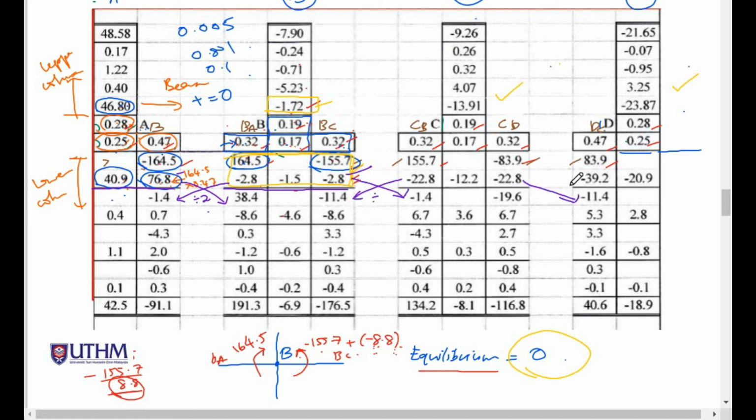Okay, divided by 2. And the process is repeating. Repeat process. Okay, so let's say here is 1.4 negative. It is the repeating process. This is 1.4 at joint A here, and negative, so it is counterclockwise, 1.4 negative. So we need an additional positive 1.4 to ensure the equilibrium condition at joint A. So thus there is no rotation at joint A.